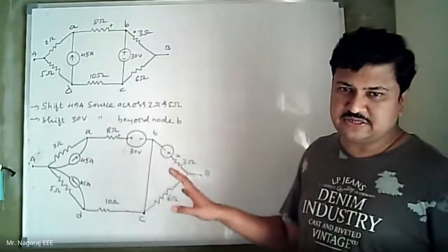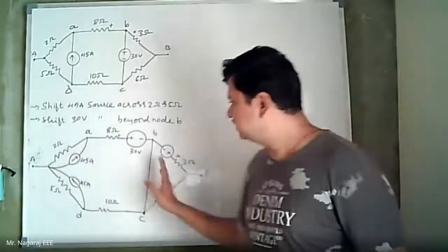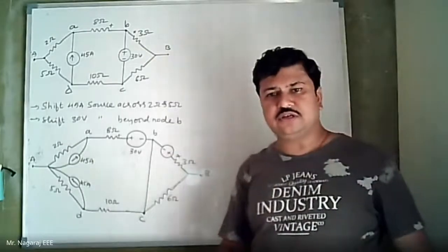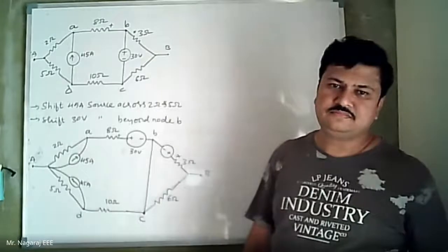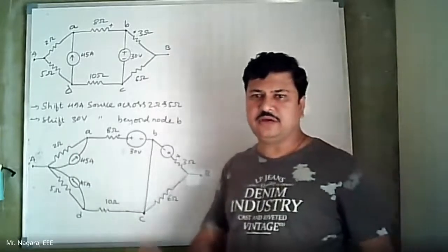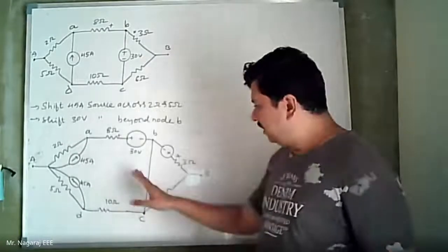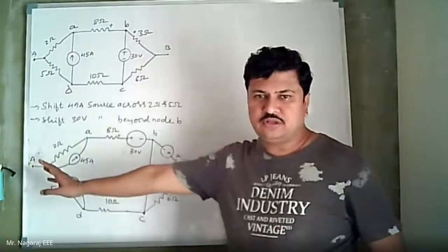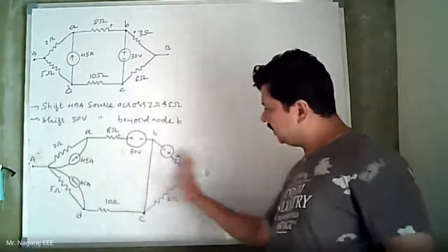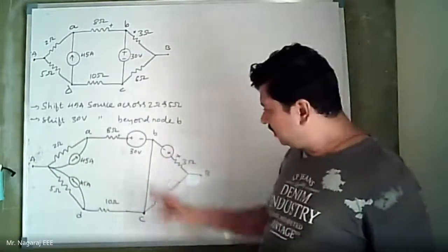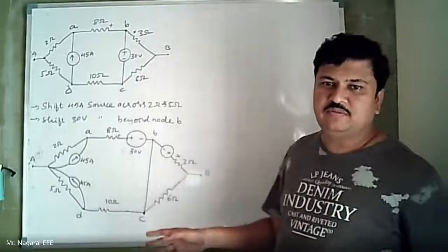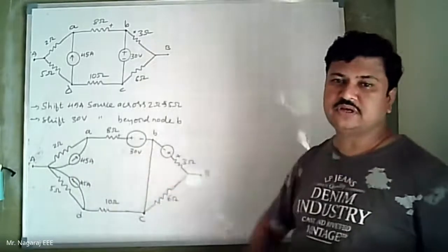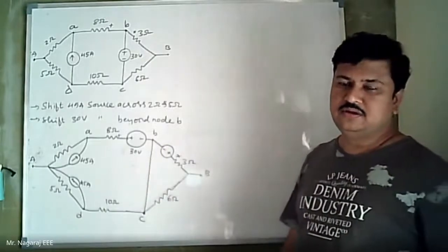It appears in this example that there are two networks on either side of the short circuit, and across short circuit my voltage is zero. Is it? This we know, across short circuit my voltage is zero. Now this network appears that there are some circuit elements connected to the right of this short circuit and to the left of this short circuit. And because there is a short circuit, we may end up thinking that the voltage is zero across both of the cases.